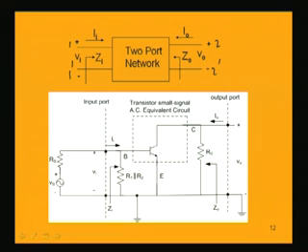So, if we look into the whole circuit at this point, between these 2 points this is the input port and this is the output port. Source and load will be external to this whole two-port system. So, this input port has all these parts along with the transistor, the circuit R1 parallel R2 and RC. Only the source and the load are external to this two-port network, and we can analyze the whole circuit in the light of this two-port network, which we are going to do next.